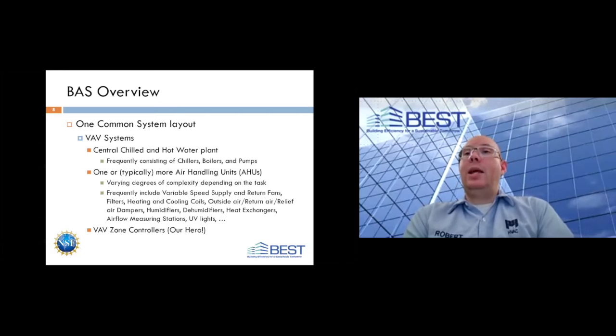And also maintain to some level the pressure within the building, trying to maintain a slightly positive pressure. Because as you all, I'm sure, know, if you can maintain a positive pressure in your building, it's much easier to control the climate within the building. It's easier to keep it clean, all of those types of things.